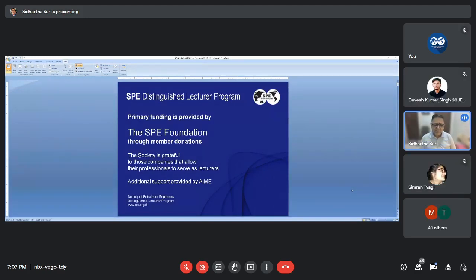When you continuously inject air, the yellow portion is the burnt zone, the zone from which all the oil, no reservoir fluid, exists. All has been displaced out ahead into the green zone, which is the banking. But what is in between, you can see the red. The red color is the high temperature zone.